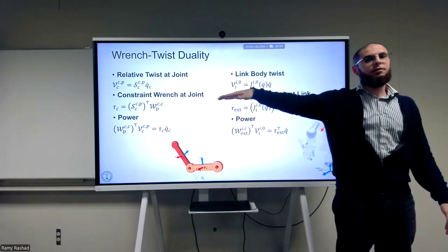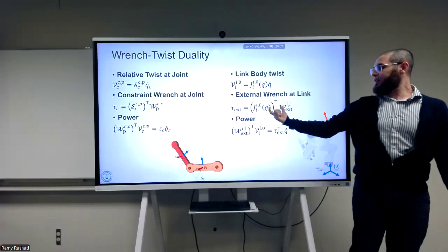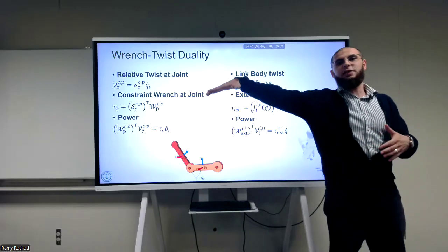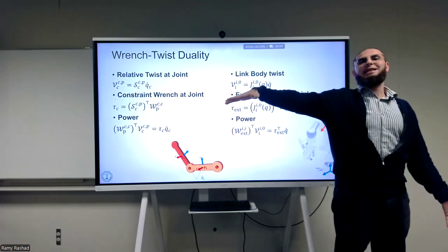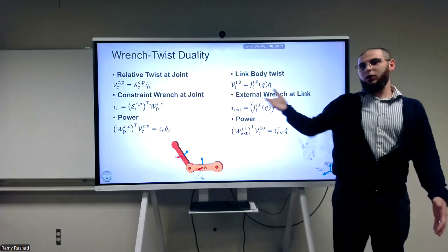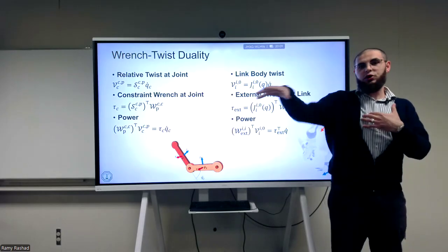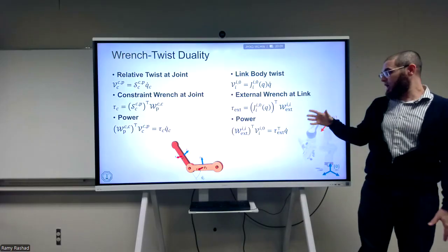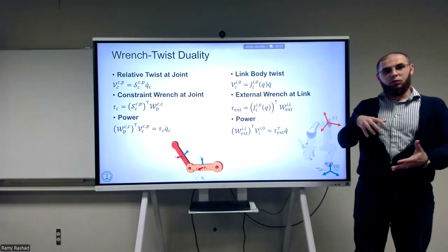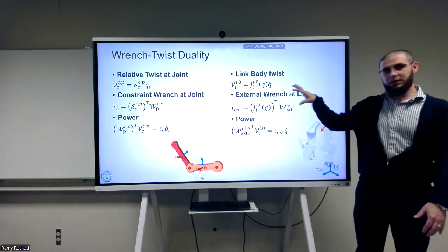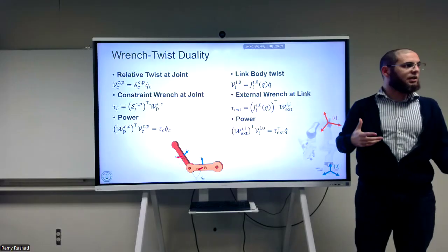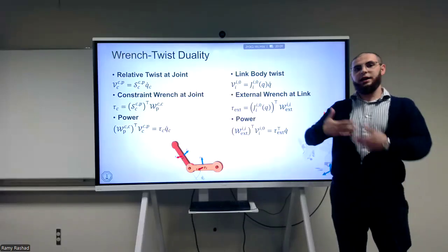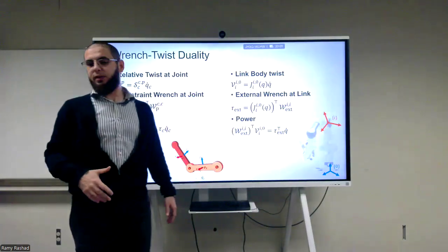It's not singularity, actually. What you're talking about here is that, because of the J, you're no longer able to apply any forces because you've reached the maximum. So the manipulability, how much force you can apply, actually depends on where you are, and it depends even in between. This is very important if you really want to design a robot, or look at the forces that I'm applying. Again, this is part of the discussion I told you. This is very deep stuff. You really need to analyze what the J looks like and how it affects the robot's performance and so on and so forth.